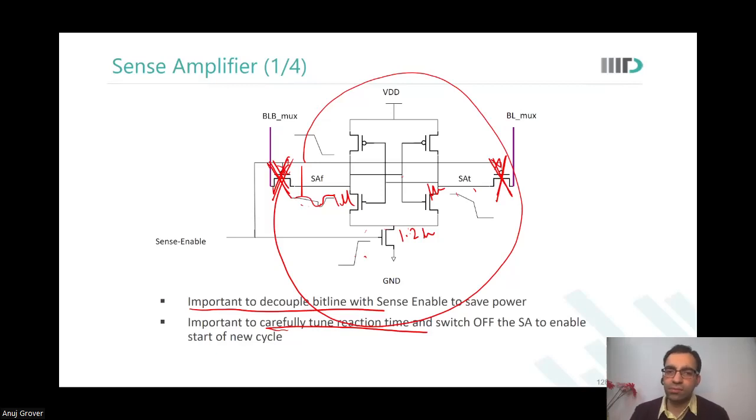It's no longer discharge. It is latching operation now. What does it exactly mean, sir? Latching means that one side will go to 0, the other side will go to 1. So if you keep this transistor bigger, you are saying that more current will flow. Okay, keep it a little bigger, no problems.